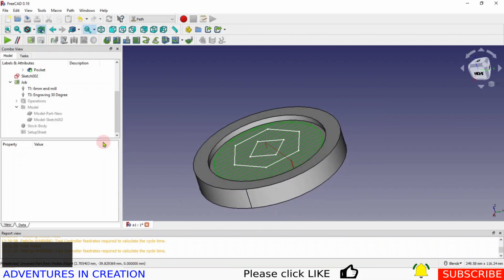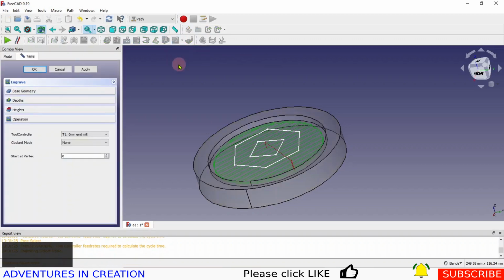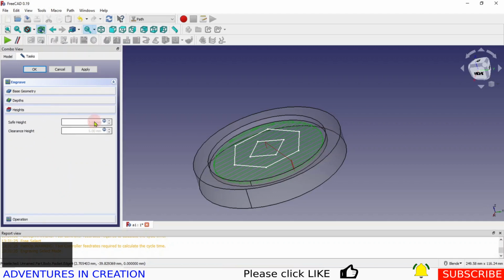Now we want to do our engraving. So we're going to choose an engraving job. And we're going to pick our 3 mil engraving 30-degree piece. So it's a pointed piece that we're going to make this with. And we're going to check our heights again. So we got 3 mil and 5 mil, that's correct.